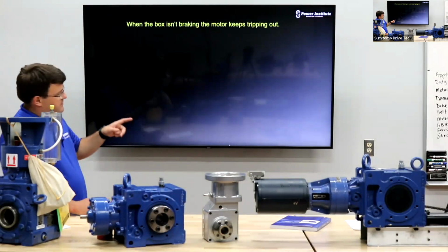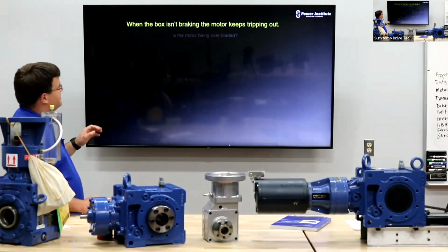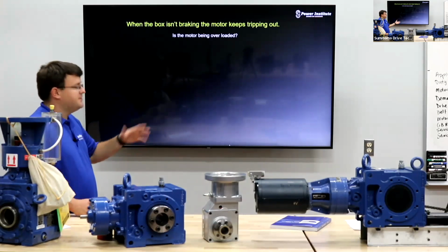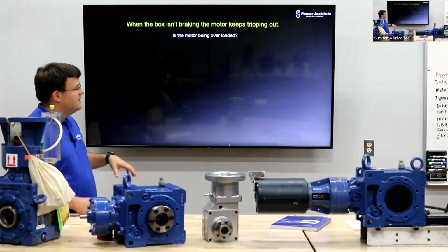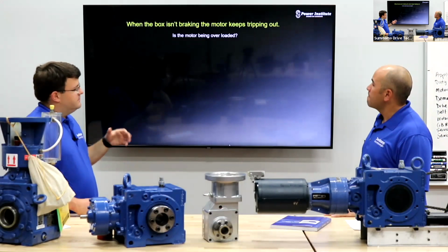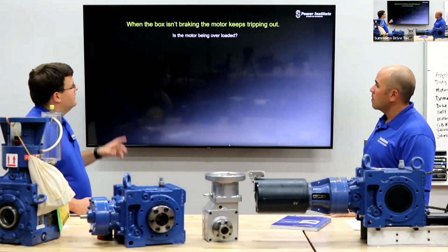Okay, so let's go back to the motor horsepower. He said it kept tripping out. So when a motor is tripping out, that means it's being overloaded in most cases. Sometimes it can mean there's an issue inside the motor, but for simplicity's sake, we'll just say it's tripping out because there's a sizing issue. Maybe it's overloaded, maybe it's being worked too hard. So let's double check this.